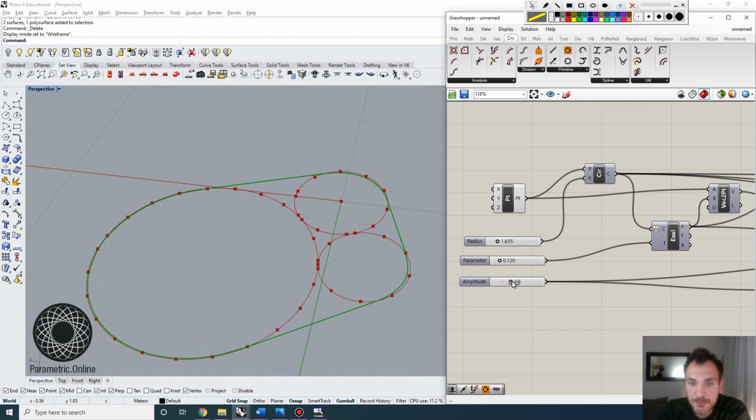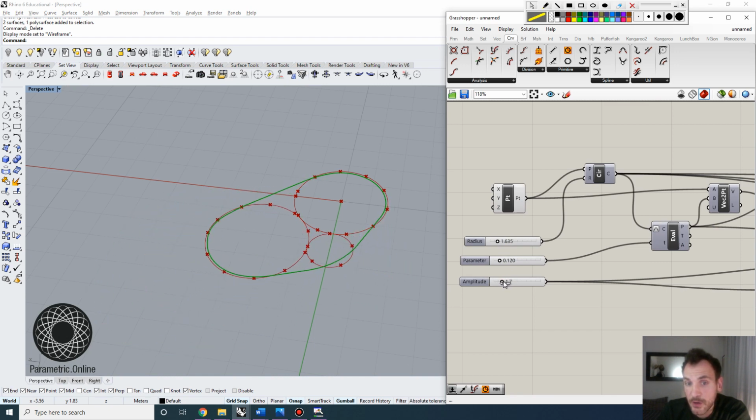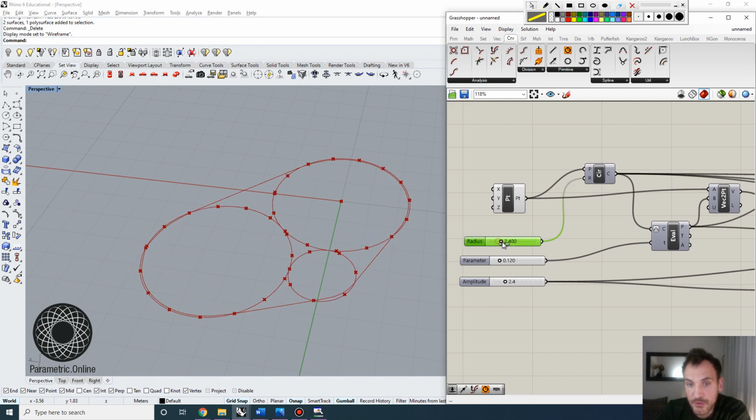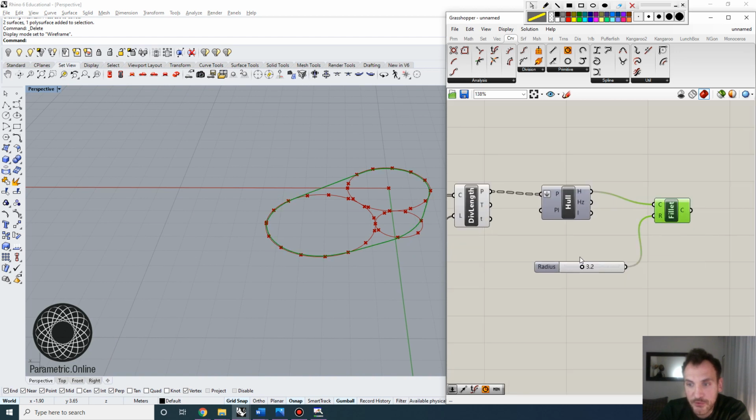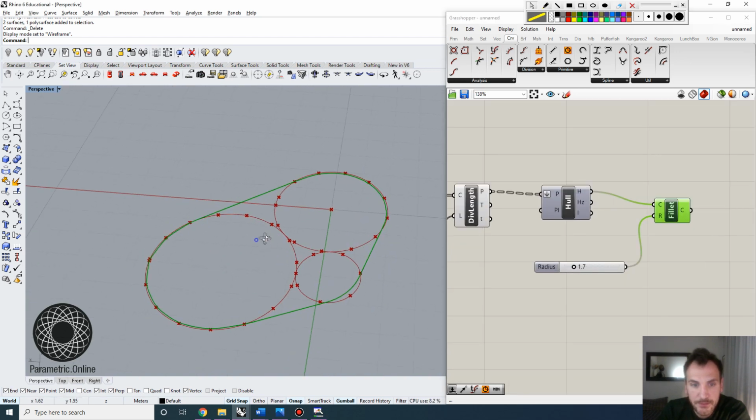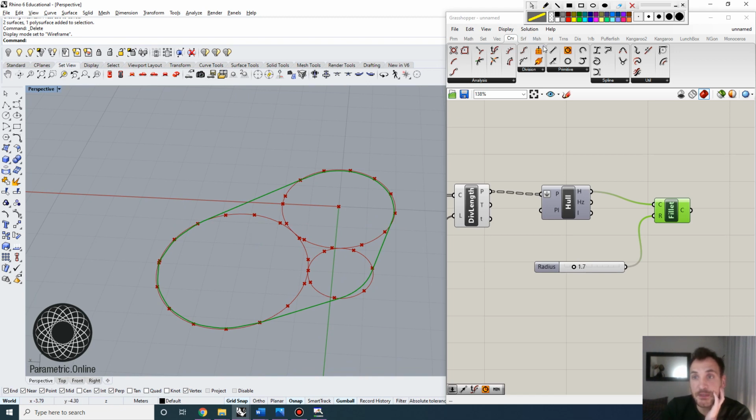And this will set up the parametric construction for our base. What we want to do next is to work with this curve a bit, and find some construction along this shape. The way I approach this task is that we can construct some perpendicular planes along this boundary, and these perpendicular planes will have 2 directions. It will have a y direction pointing in some direction, and perpendicular to it we will have an x direction.